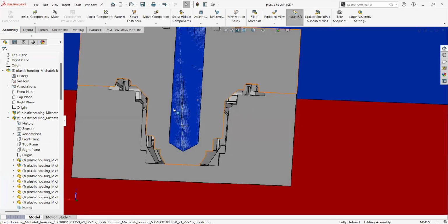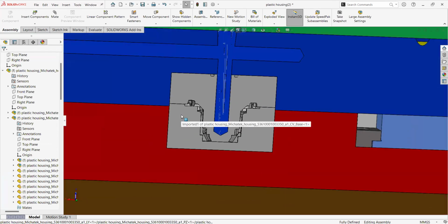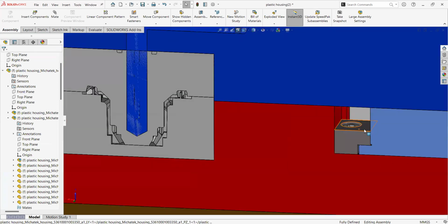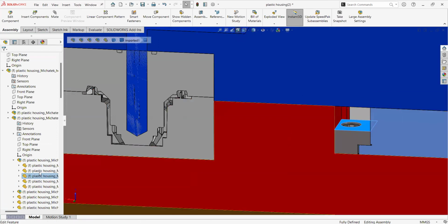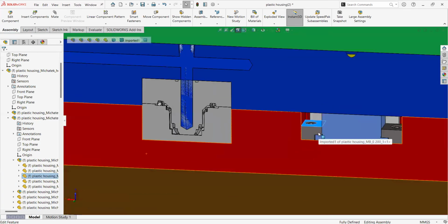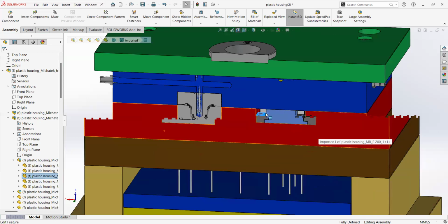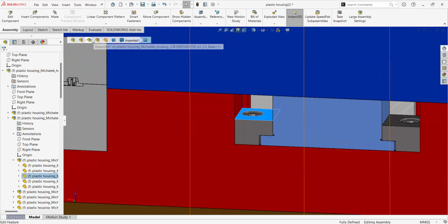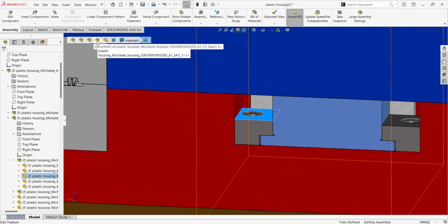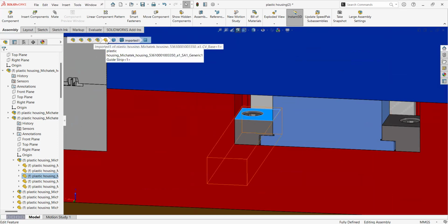And we can explore the model, and we can always pick internal components, for example, that we are looking for. So for example, I pick this one, and once again, I have here the options, and I have the highlight at the left. But there is one extra trick that is going to help you to explore the assembly. And it is the breadcrumbs here at the top. As you can see, I have here some icons for assemblies, then an icon for a part, and then a body, then a feature, and then the face that I'm selecting.